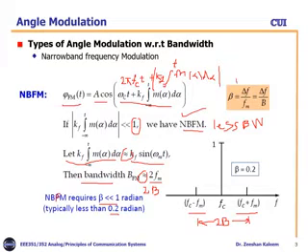You know that beta can be calculated as delta f over fm, which is delta f over B. This is the modulation index equation which we already derived in the previous lectures. If you are not familiar, then please go to the previous videos. This spectrum is plotted for beta equal to 0.2, so it is less than 1.